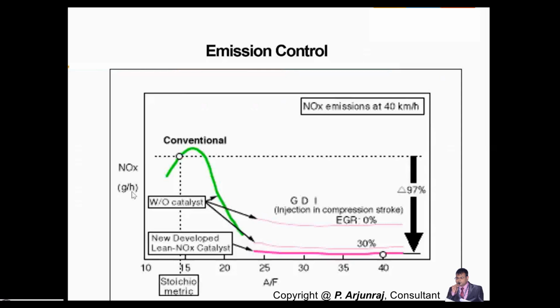So we can reduce CO2 only if we reduce CO in the system. How can we reduce CO? By different injection strategies, multiple injection strategies, and the proper amount of air fuel mixture, for which GDI is going to help. Even MPFI is good, but comparatively it is less efficient.